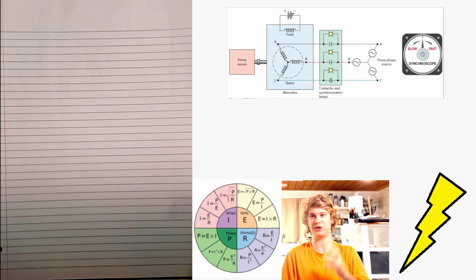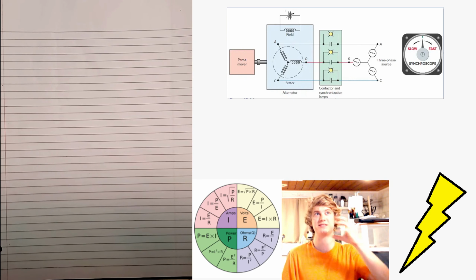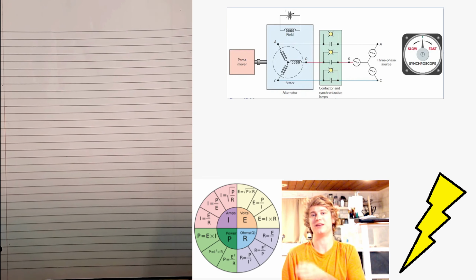Phase is the position of a point in time on a waveform cycle. So because the phase is the position in time where it is, we can comprehend that they're 120 electrical degrees apart, as we went over with the sine waves of the three-phase system. So again, you have three separate voltages with the same frequency and magnitude. They just have a different phase, and that is 120 electrical degrees apart, okay?